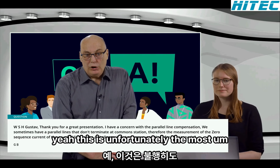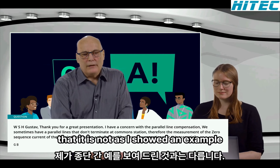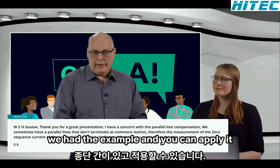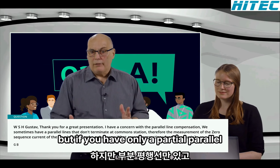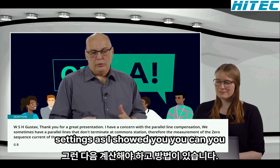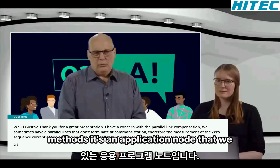This is unfortunately the most common condition for the parallel line, that it is not, as I showed in an example, end-to-end. In some short lines in distribution, you have the end-to-end as we had in the example, and you can apply it. But if you have only a partial parallel line and you don't have access to that, then you have to consider it in the settings. As I showed you, you then have to calculate, and there are methods. There's also an application note that we can dig out.